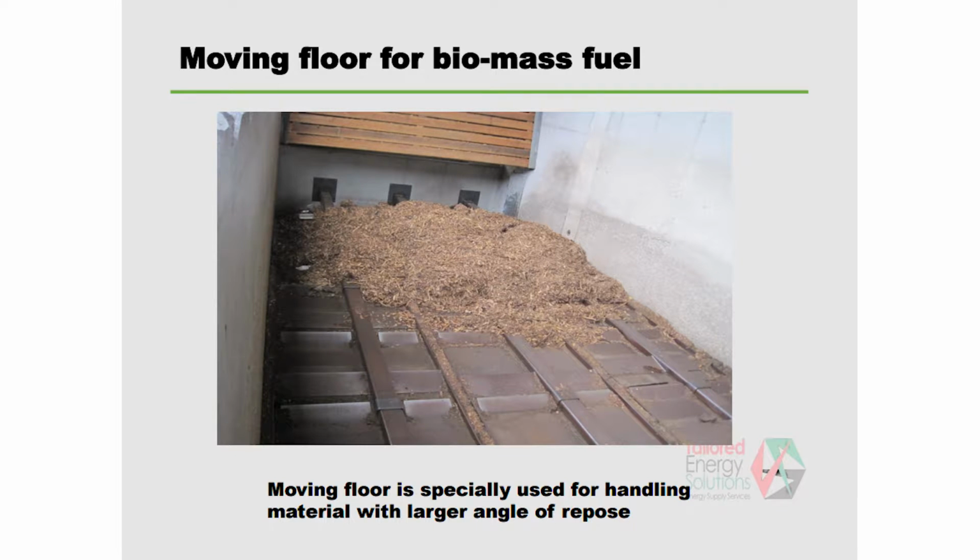And for wood waste, you use a moving floor. Why don't we use the traditional systems for wood waste? Simply because of the angle of repose. There is no flowability available, so we have to use a different type.